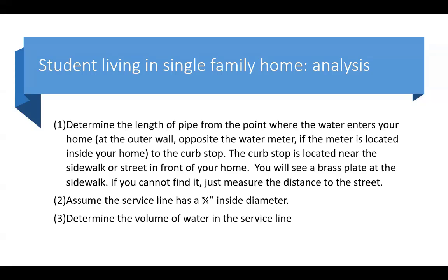You'll also need to determine the length of your service line. So you'll determine the length from the point where the water enters the home, on the opposite side of your meter, on the outside wall, to the curb stop. You'll see a brass plate. You want to do this sooner.